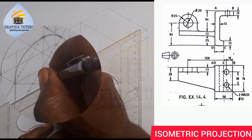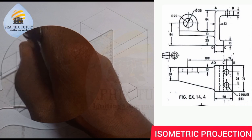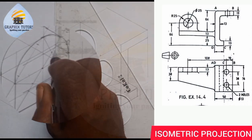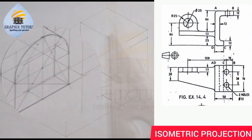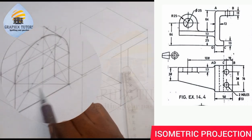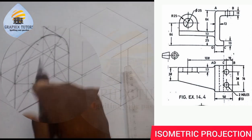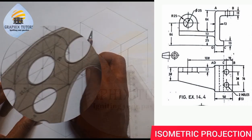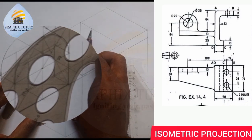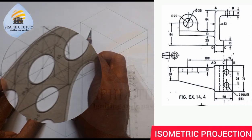So this is the box I want to form out here at this point and at this point, right? And at this point, or this point I marked. So one of the easy ways you can do is to look for a circle that will best fit in this place, or you just construct it. So I can actually use my French curve here to look for the best ellipse that will fit into this box. If I use this, it looks like the best ellipse that will fit into this box. Hope you can see that. So I'll just draw this out.